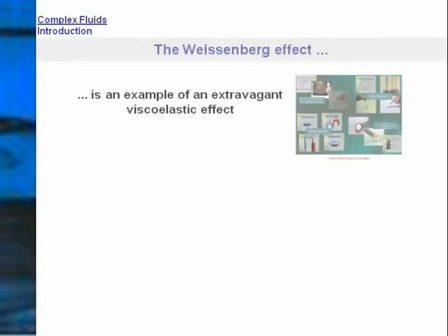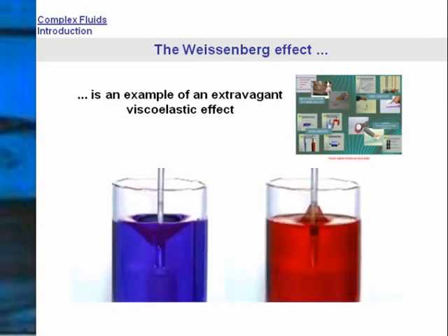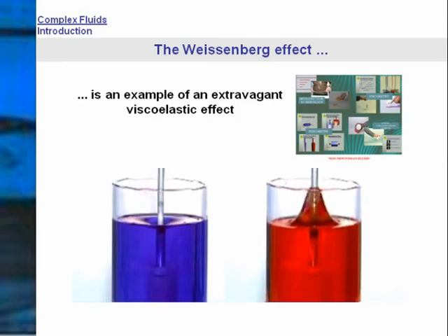In some ways, extravagant viscoelastic effects can be demonstrated in basic rheometrical flows, such as steady simple shear flow and uniaxial extension. Indeed, the rod-climbing Weissenberg effect, associated with normal stress effects in shear flow, is a classic example of what we have in mind. We have purposely decided not to go over old ground in the present film, and we simply show explanatory clips here, referring the viewer to the relevant Institute of Non-Newtonian Fluid Mechanics film. The blue liquid is Newtonian and the red liquid is viscoelastic.